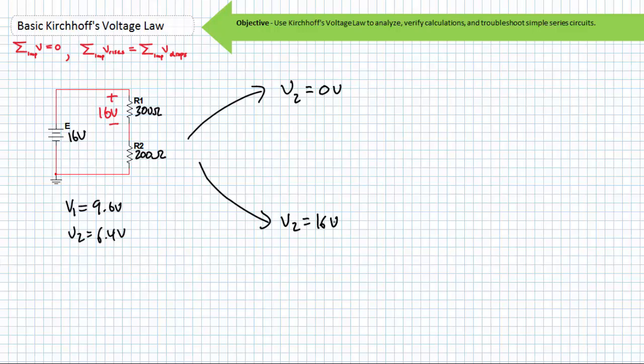Dealing with the first scenario, we find a circuit exhibiting all voltage drop across one resistor and none across the second. This being said, the circuit is clearly in obedience to KVL in that a 16 volt rise equals a 16 volt fall plus a 0 volt fall. Let that at least be a small comfort to your softly weeping lab partner.